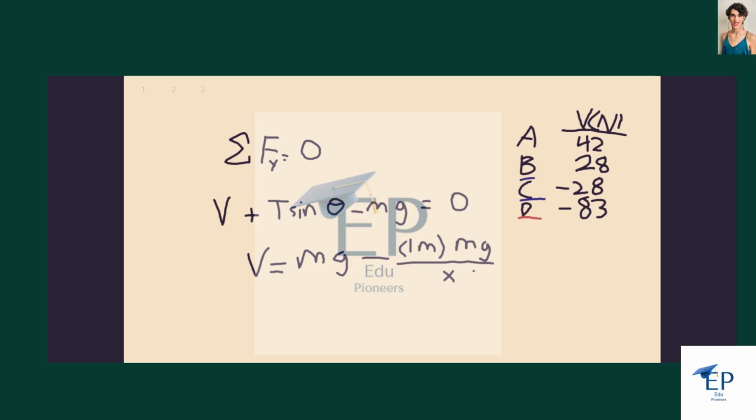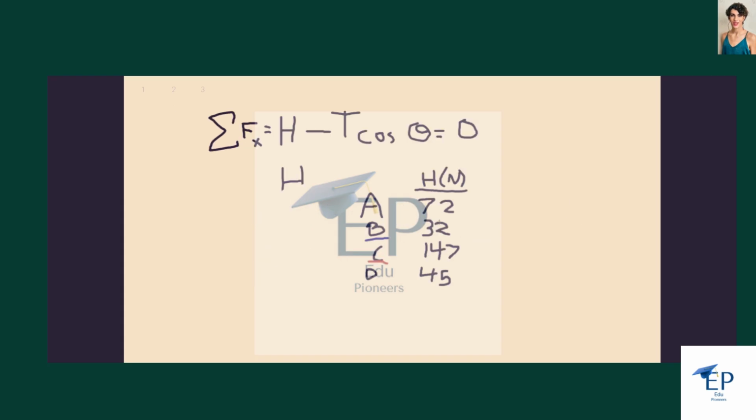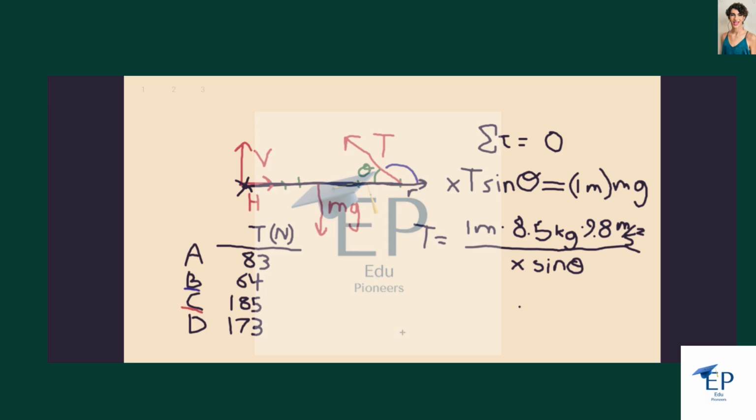So I'd avoid C and D. Case A got mediocre vertical hinge force, and mediocre horizontal hinge force, and fairly small force of tension in the cable. So case A might be okay, but as an answer, we'd say alternative B is preferable, and we would avoid both alternatives C and D. And that's the end of that problem.